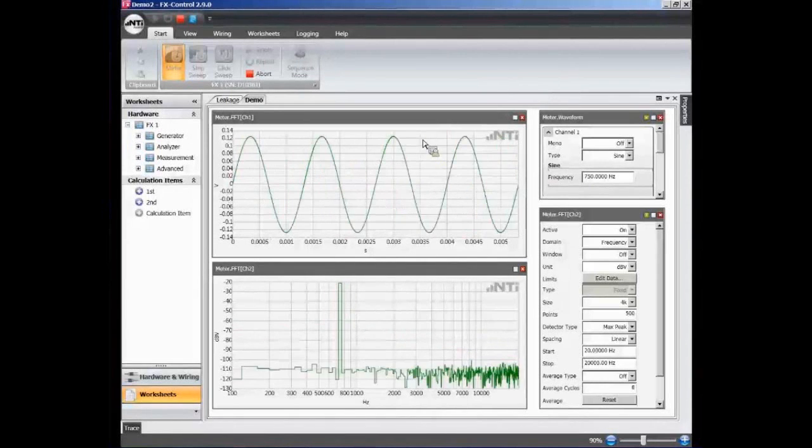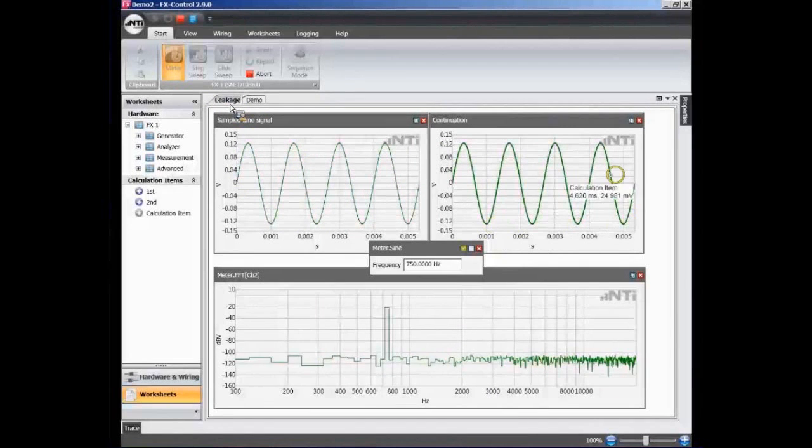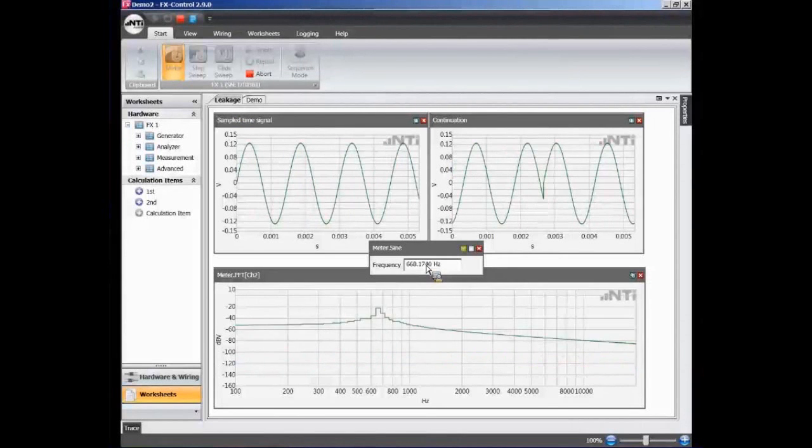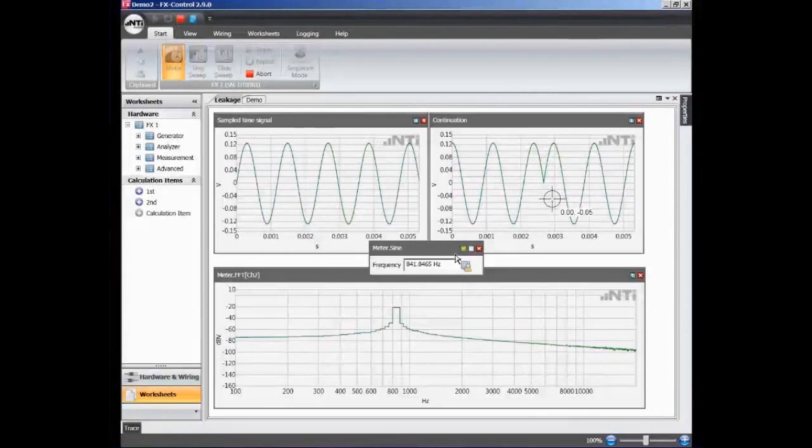Let me show you that in another, more detailed picture. Here we have again the generated sine signal. Here we have the time signal as it is captured and repeated by the FFT calculation, and down here the spectrum. Now I do the same as before. I amend the frequency, and you see immediately we get these discontinuities, these steps that are causing our smearing down here. And I can have different shapes of this discontinuity. You see it here. This depends on the exact position of the sine wave in our capture window, and so on and so forth. But this is the root cause of our smearing.